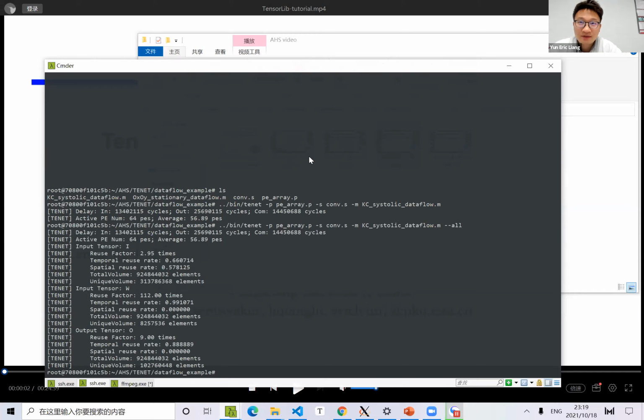We can see that the final latency of this data flow is bounded by the output latency, because the output image size is large, making parallelization in the channel dimension require reading and storing output multiple times. To reduce output store latency, a possible solution is to maximize output data reuse. So here we can use another data flow called output stationary data flow.